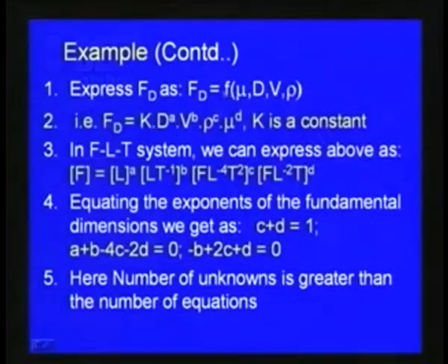So, the first step in this Rayleigh's method is to express this Fd, the drag force, as a function of these important parameters mu, d, v and rho. So, we write the drag force Fd as a function of mu, d, v and rho in this first step, and now we have written a function.